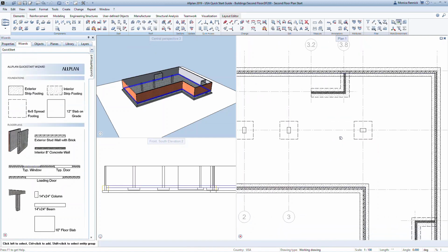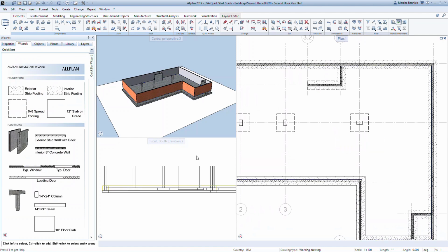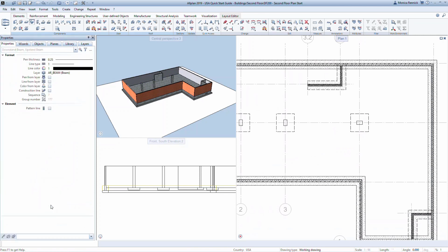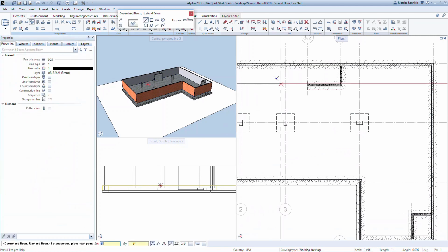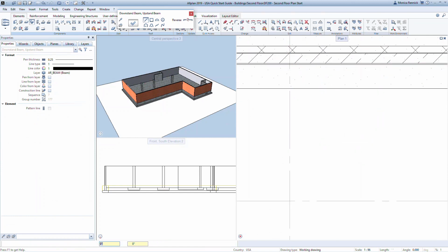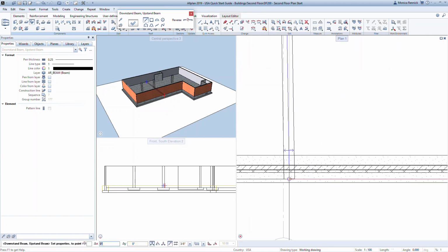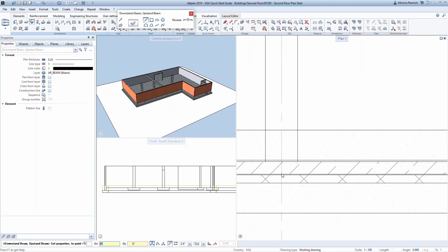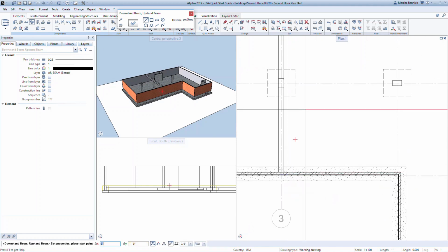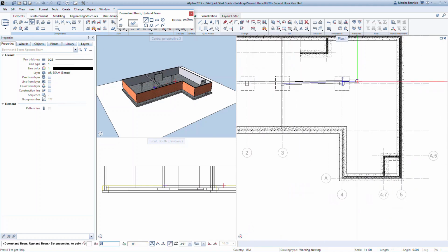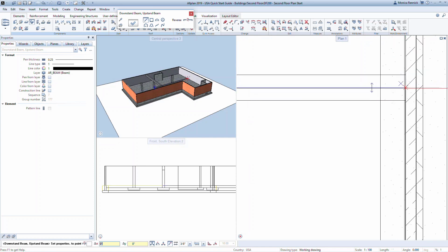We can now confirm what's been drawn in the 3D animation view. Notice the wall and column heights are accurately taken from the plan model that was predefined in the building structure. Next, let's model the beams the same way that we've seen. Double right-click on the beam element in the wizard. Now click on the model where you want to model the beams. They will span along grid line 3 from wall to wall, and along grid line C from column C3 to the exterior wall.